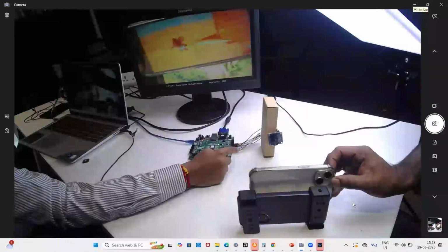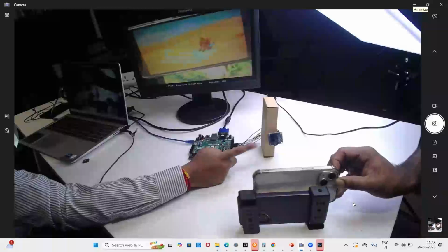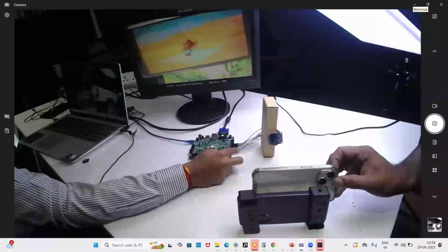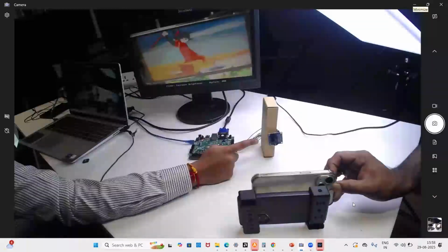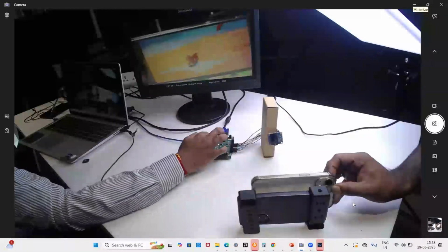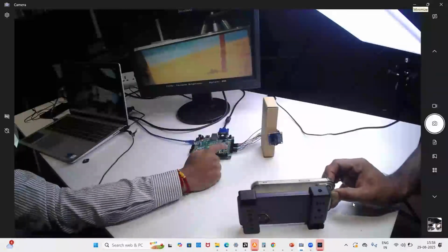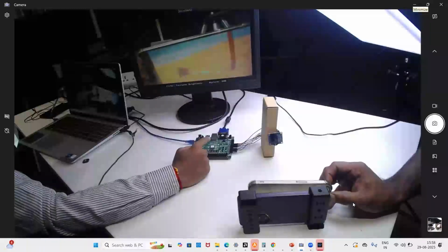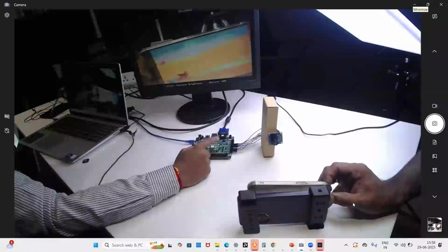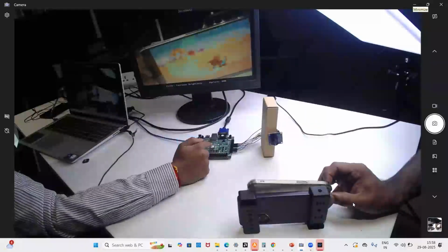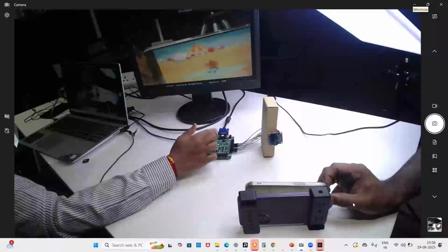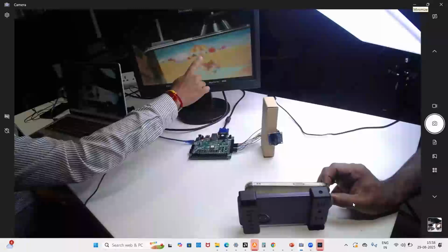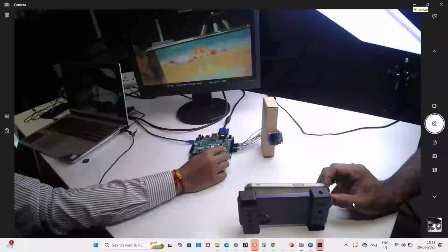This is the general purpose input output which we have used to give this camera an input interface. The pixel data, whatever you receive from this end, is stored on the local VRAM given by this Nexys A7. This VRAM stores 307,200 pixels of intensity information continuously and writes it from this part. We read those pixel data, convert it to 12-bit and pass it to the display.